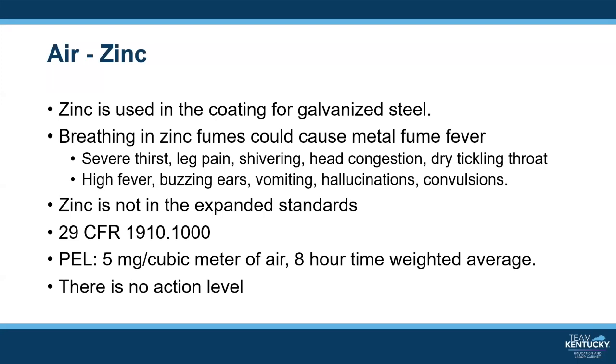If good local ventilation is not possible, you should wear an approved respirator, which will fit inside the welding mask. The respirator will collect the welding fume particles and keep them from entering your lungs. A paper dust mask may not be adequate.